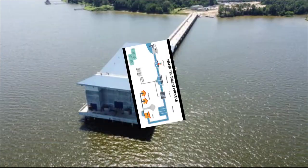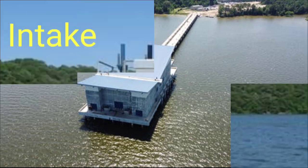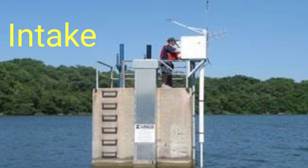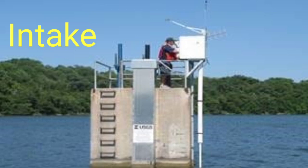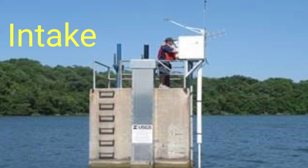The basic purpose is to provide calm and still water conditions, so that comparatively pure water may be collected from the sources. After the collection of water from the intakes, the first step in the treatment process is to screen the water to remove the larger items of suspended material such as plants, trees, animals and other debris present in water as they are collected from the reservoirs, sea or the rivers. As the name suggests, these are captured and removed by the use of large metal screens.